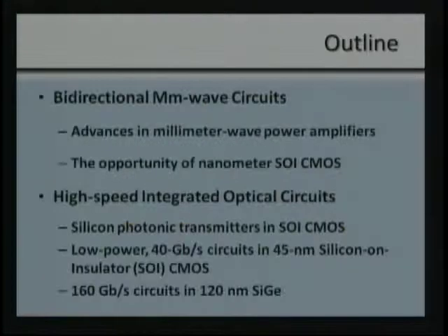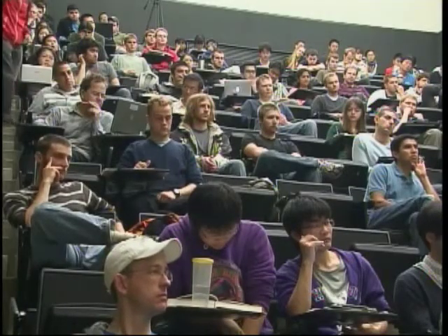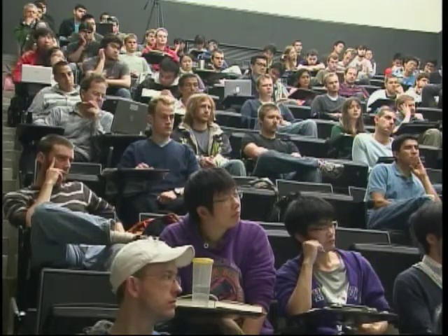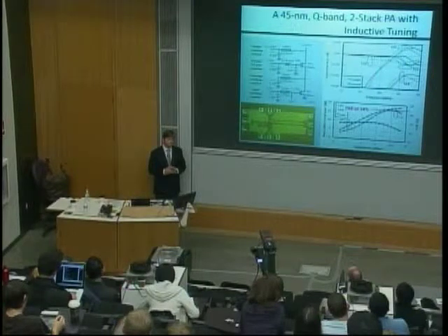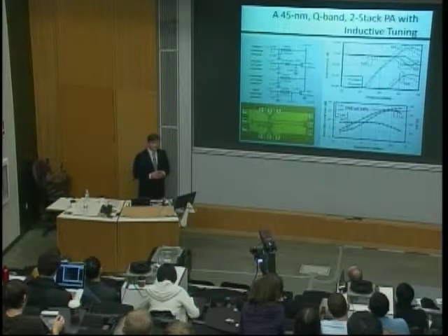So are there any questions at this point? I'm going to switch gears a little bit. Yes? Bulk biasing, or not bulk biasing, but biasing up the transistors for these SOI processes. Is there any sort of special care or sequencing you're taking when you're powering up these devices so that you don't break down the devices while it's being turned on?